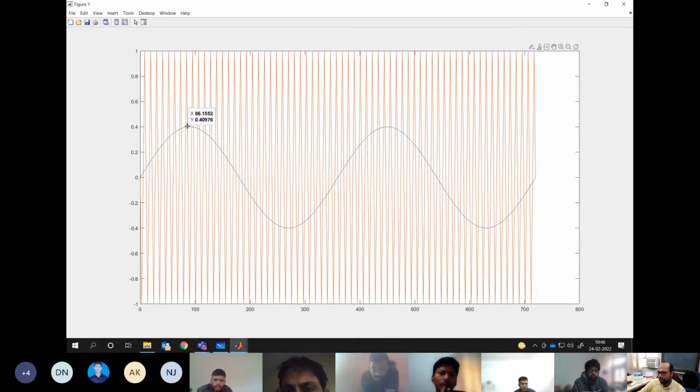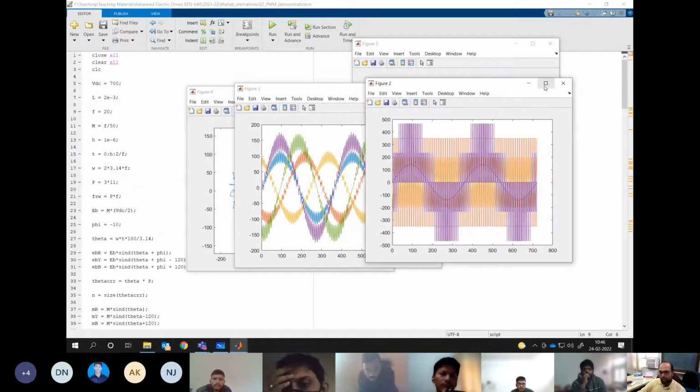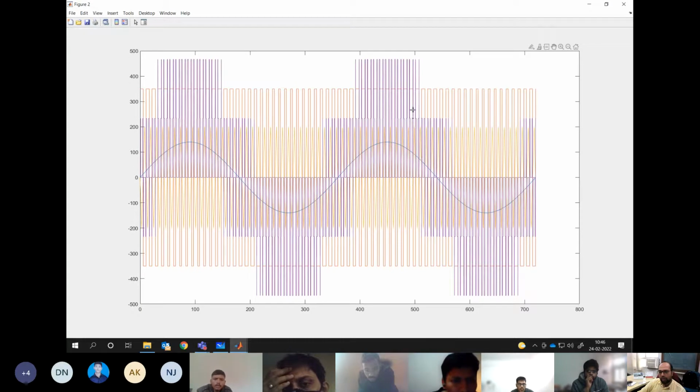You understand my point? So if you are going in V by F mode, gradually your modulating signal will increase from 0 all the way up to 1 peak value. Understand my point? Okay. Now, if you have got that understanding, let us try to see how the pole voltage is coming. What we have seen, basically the width is changing, going on increasing and then coming back to 0.